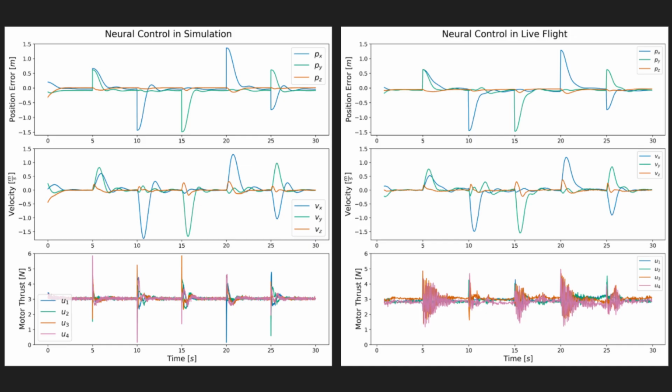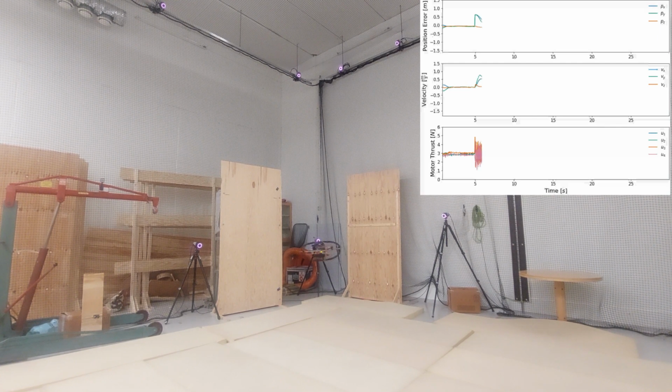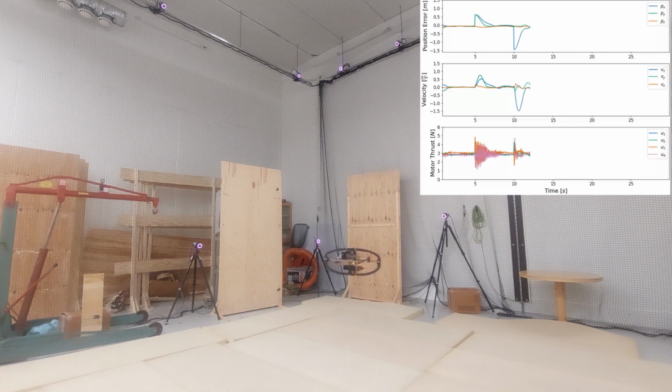We have demonstrated the capabilities of the pipeline by deploying a trained policy to an aerial robotics platform. The results show that the module is able to achieve close to sim performance in the real world. By being able to build the neural policies together with PX4 on off-the-shelf hardware, the pipeline is accessible for most researchers. Since it is built together with PX4, the PX4 autopilot software can handle everything outside the policy use case, like safety features or tools like Kalman filters.